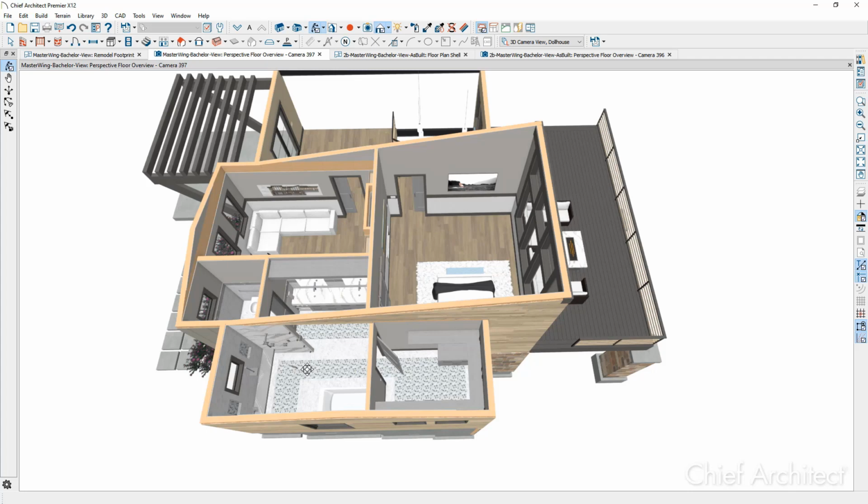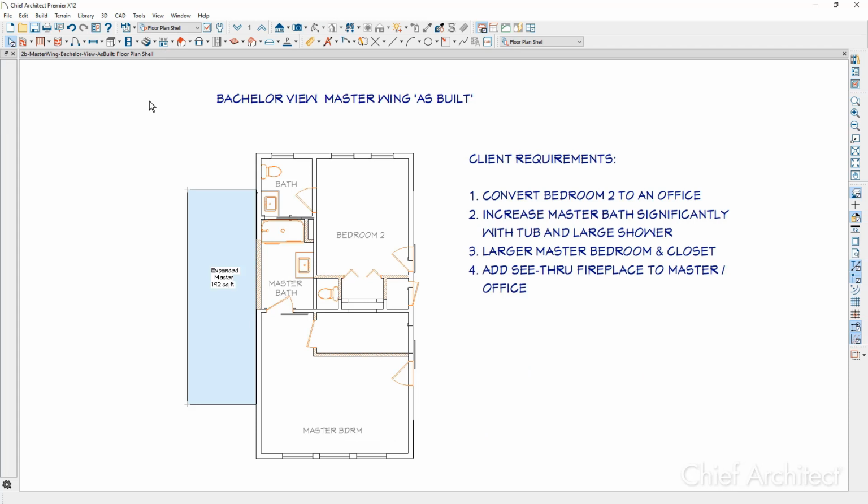Let's begin the project by making the changes into the as-built for the addition. With the as-built plan open, you can see the areas highlighted in orange that have been removed or demoed out of the design. I've used the reference display feature to superimpose that original as-built over the top of this existing plan. You can easily toggle that on with the reference display tool.